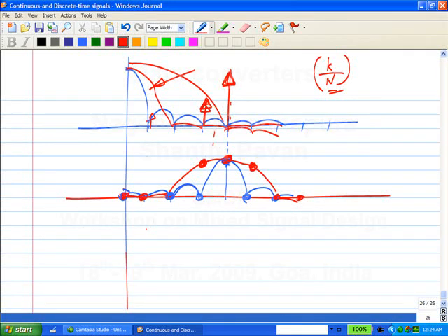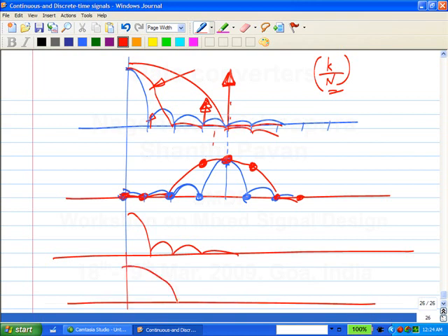Yeah. We don't modify the amplitude of these samples. That's correct. But with these other windows, the amplitude of samples get modified. That's correct. So that effect is described by this convolution. When we have a rectangular window, we are convolving it with this. When we have a Hann window, we are convolving it with this. So the entire effect is described by this one. Okay. Now, yeah, it looks like it is being modified, but this is what it means: that it is getting convolved with something like this.